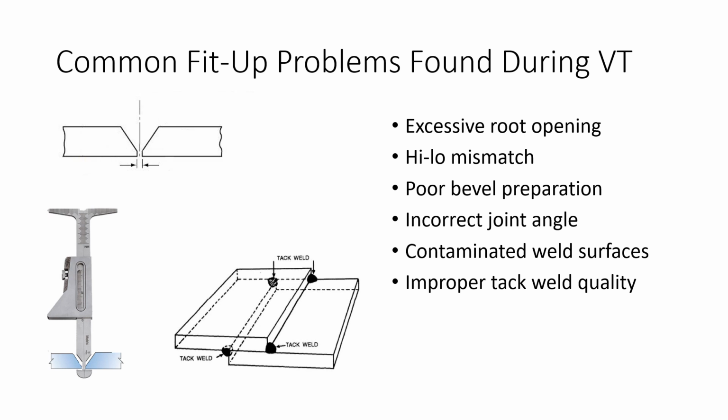High-low mismatch. Hey, is the pipe concentric? Have we got our pipe? If you get some thin-walled pipe, it looks circular, but you go to tack that stuff up, the Schedule 10 thin wall stuff, that stuff looks like an Easter egg.